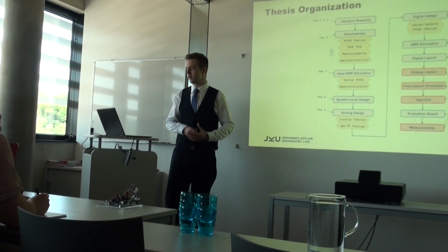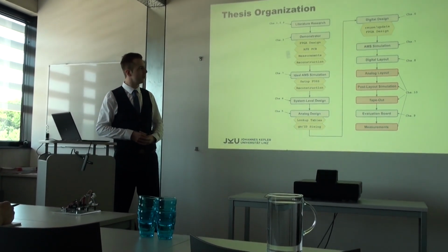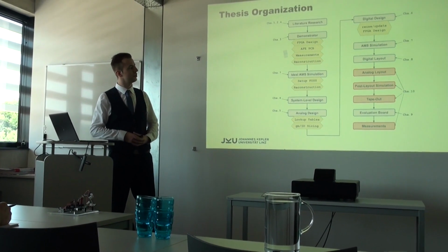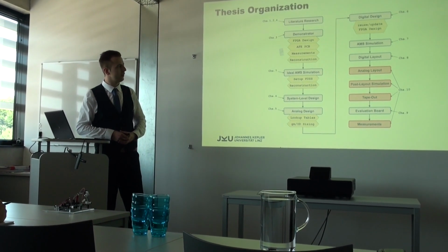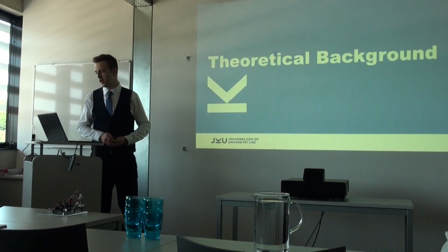and in the end I wanted to build my own ASIC design, so my transistor level design. So I made a system level design, designed the transistor level circuits, made the digital layout, and mixed signal simulation. The red boxes are the outlook, what will hopefully be tackled in the future.